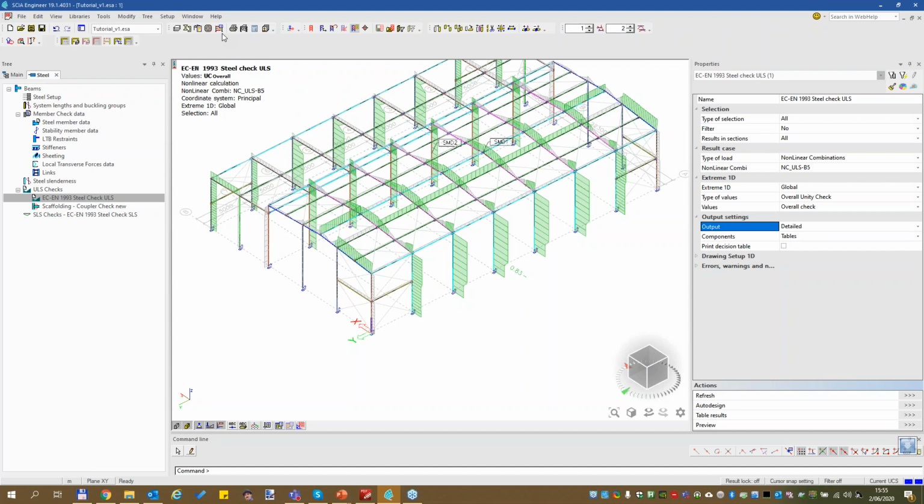It's unstable. In those cases, it's really interesting to execute a stability calculation in order to find those weak elements and adjust them accordingly. Usually it's either a member that is buckling by the given load, or you have too many hinges in your structure, which leads to too many rotations, which then leads to a mechanism or to instabilities, where your member is just rotating around its own axis, for example.